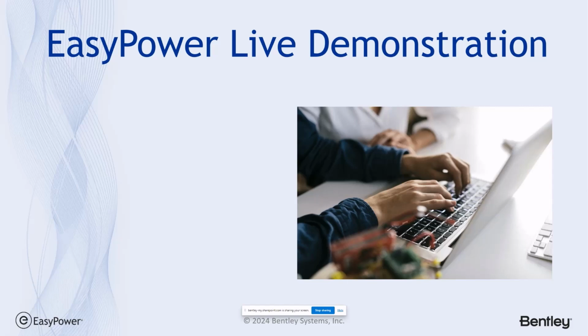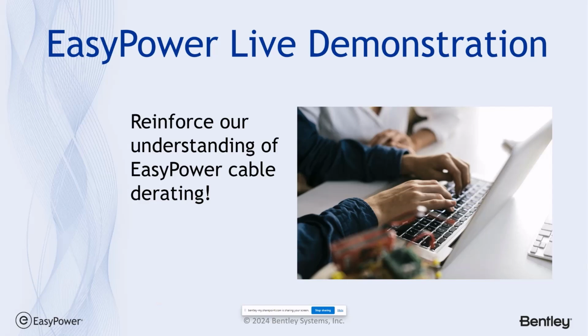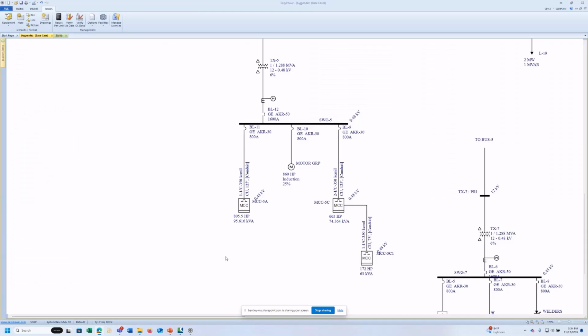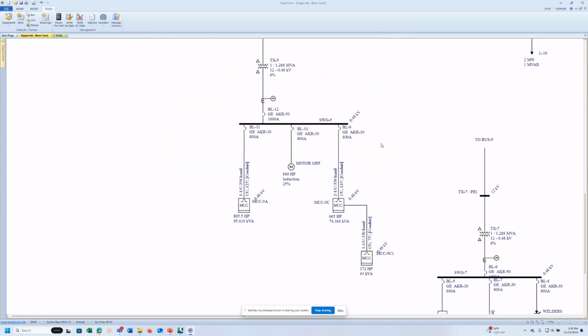So now we're going to go ahead and move into the EasyPower software to reinforce our understanding of this cable ampacity derating topic. So excuse me for one moment while I switch into the software. We're going to take a look at the bigger.dez sample file, which you can get to from the File Open File menu, and then going into our samples directory, opening bigger.dez. We're going to take a look at the feeder cable off of switchgear 5 out to MCC 5A.